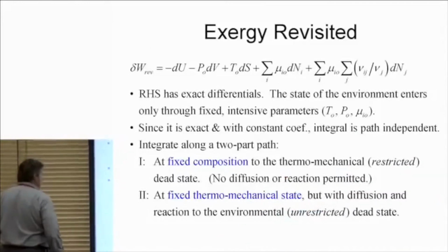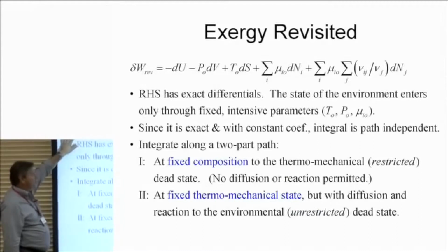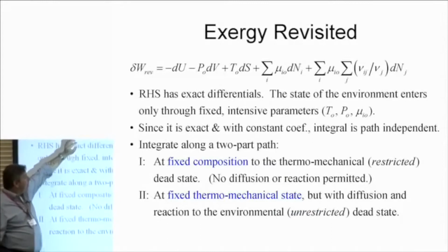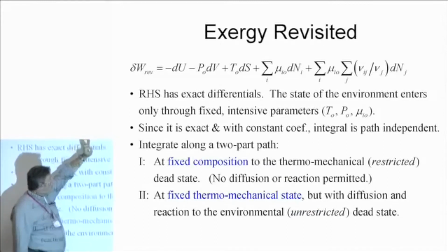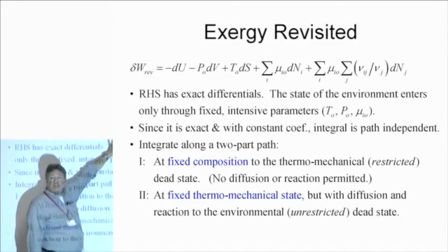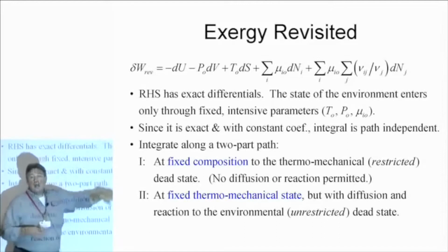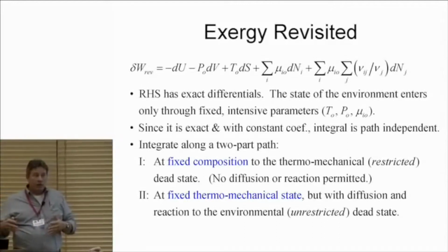Okay, so this is what we got. Small amount of work, differential amount of work, reversible, so the best I can do comes at the expense of internal energy, can't get at the boundary work, might get a freebie for heat transfer. I can get a freebie from chemical potential of species that come from the atmosphere into the system that are drawn in. So my isooctane will draw oxygen from the outside world. I get its chemical potential.